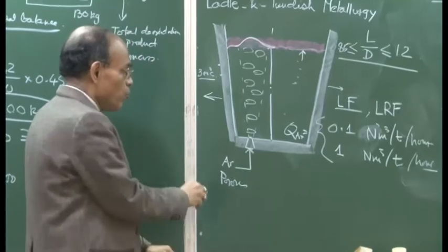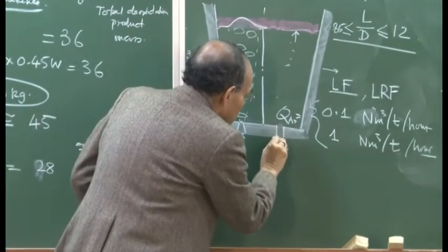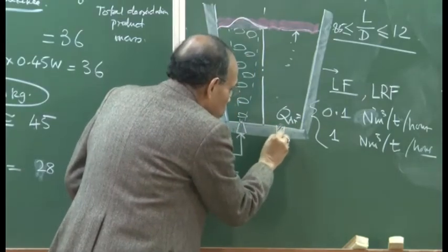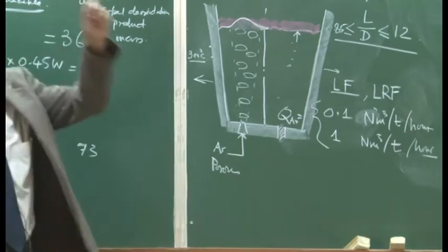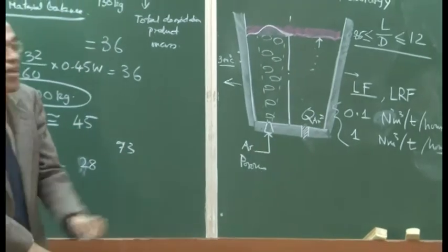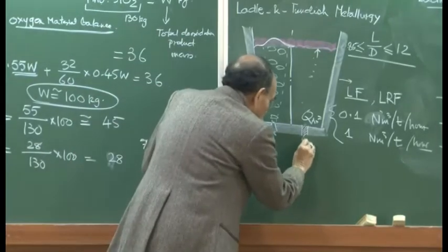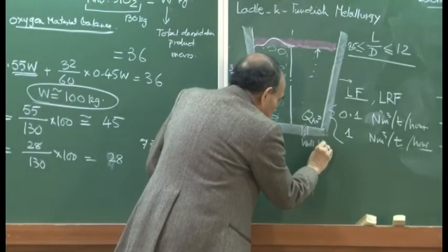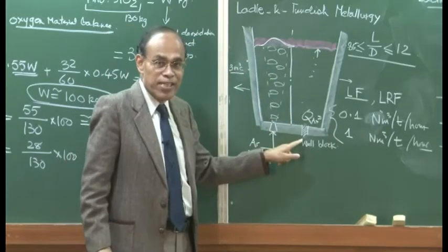Also, we have a well block here, and that well block is basically to drain molten metal out. Ladles will never be tilted like the furnace. All ladles are equipped with a bottom pouring facility. So, this is the well block. There is a little nozzle here, and we will study that there are metering nozzle facilities here.